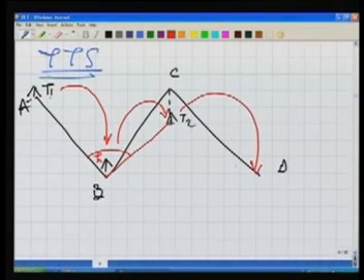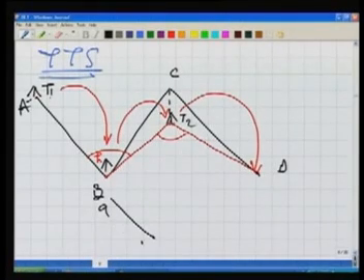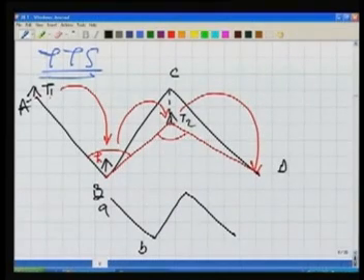So what happens in that case? Now the theodolite is here, not here. The theodolite is at the same point where my target is, and next I measure this angle. If you plot it, AB will be plotted like this, A, B. Now at B we are plotting the wrong angle instead of the correct one. This is the correct one; I plot the wrong angle.